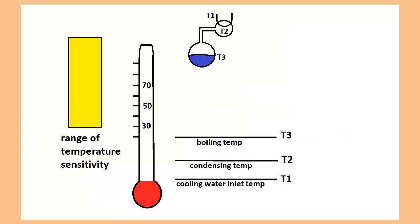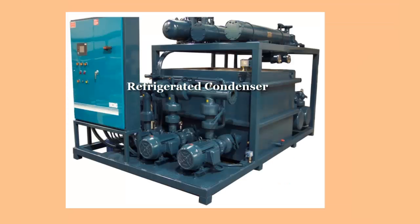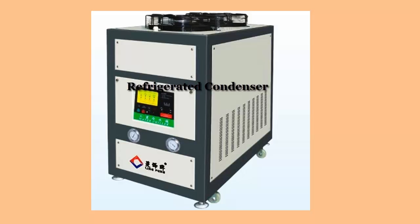Refrigerated condensers can move the temperatures down to a safe level, and these are applied in industries like pharmaceuticals, where production volumes are small and the product selling price is high. But refrigerated condensers are too expensive to operate for large-scale commodity producers. Refrigeration addresses the limitation imposed by plant cooling water temperature.